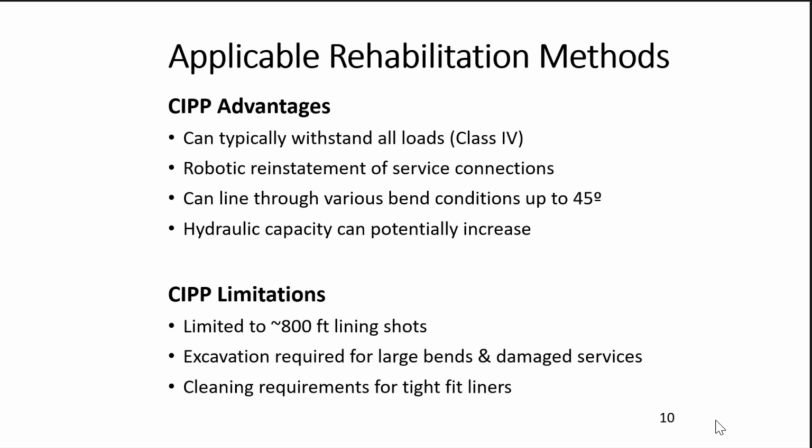In general, the liners are relatively thin. They're strong but thin, and so it's not like slip lining where you're losing quite a bit of capacity. The capacity loss is much less. And typically, because you're going in and cleaning out that pipe at first, you're generally actually improving your hydraulic characteristics. Some of the limitations, you can't do as long a reach. I know these are in feet, but maybe 100, 200 meters might be normal for a max, whereas with slip lining, you can go quite a bit, 500 meters or even farther.